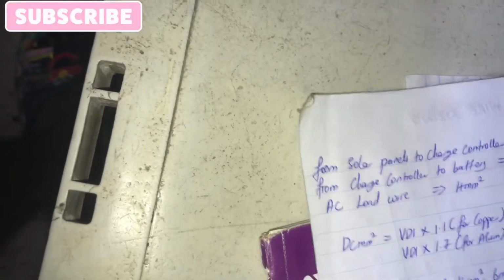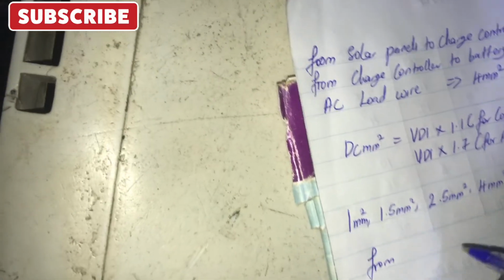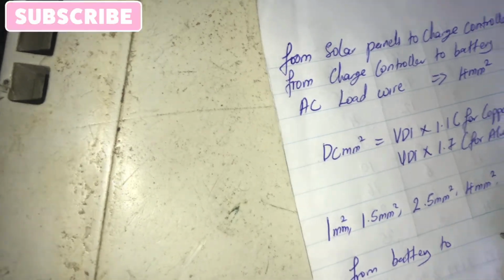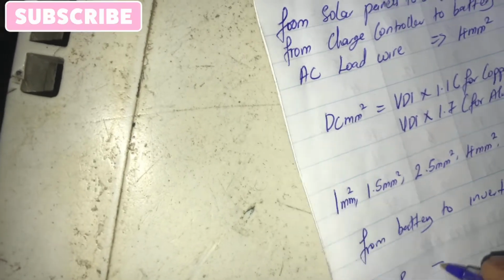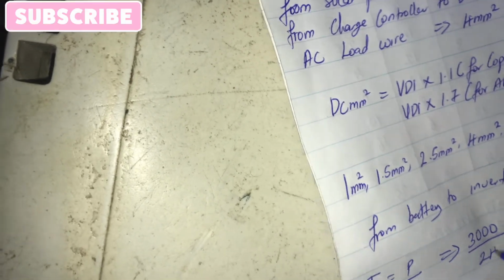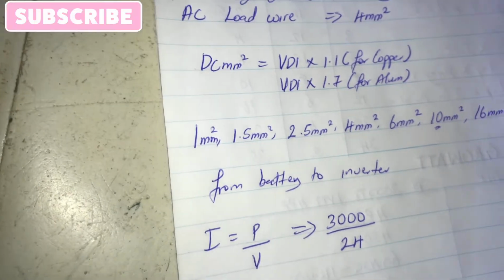Then another thing I want us to do, but this one I want you to try on your own, so that I will be sure you are following. From battery to inverter, I want you to try this one, knowing that we first of all calculate for the current, which is I equals P over V, and the power we have here is 3000 watts over 24 volts. So I just want you to pause the video and do it really quickly before I show you the answer, so that I'll be sure that you are following me.